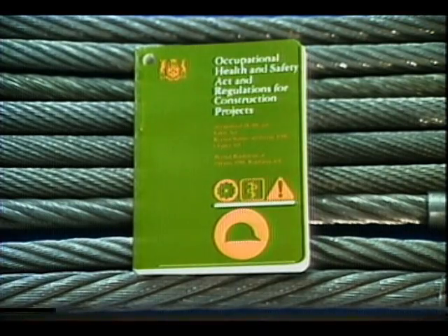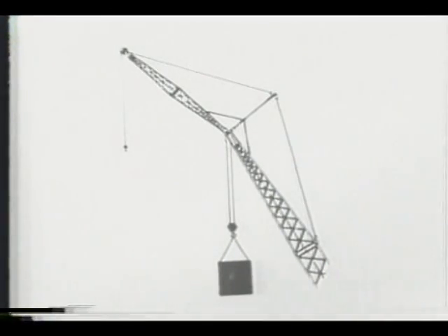The regulations go on to state the allowable reduction in diameter for various size ropes. Steel wire rope that is static or used for pendants should not be used if there are 3 or more broken wires in one lay in sections between end connectors, or if there is more than one broken wire at an end connector.